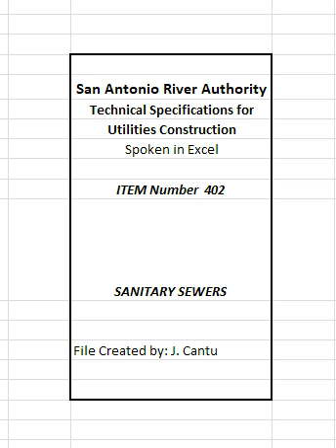The polyethylene lining material for pipe and fitting shall be virgin polyethylene ANSI/ASTM D1248, compounded with inert filler and with sufficient carbon black to resist ultraviolet rays during storage of the pipe and fittings. The polyethylene shall be bonded to the interior of the pipe or fitting by heat. Polyethylene lining in pipe and in fittings shall be 40 mils nominal thickness. Minimum lining thickness shall be 30 mils. Procedure for sealing cut ends and repairing field damaged areas of outside coated and interior lined ductile iron pipe and fittings shall comply with manufacturer's specifications.